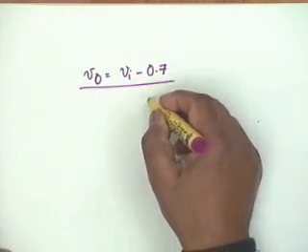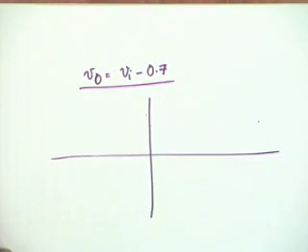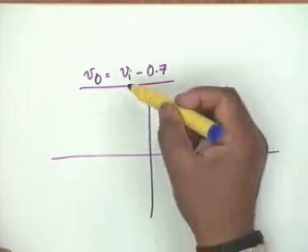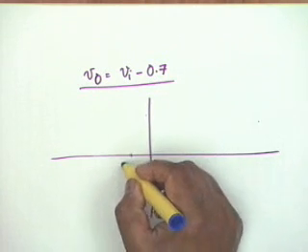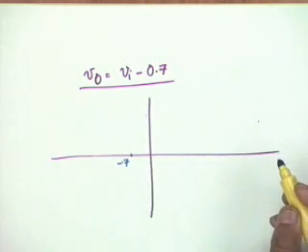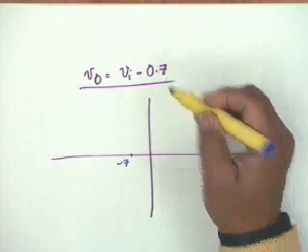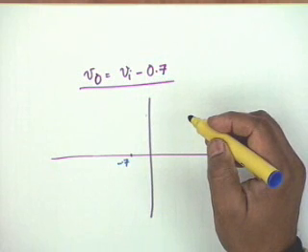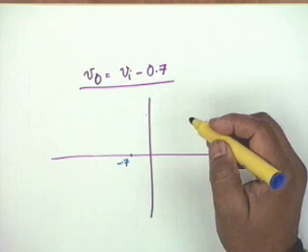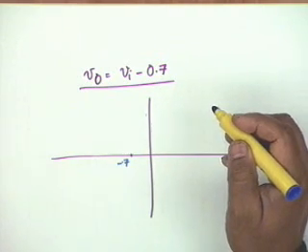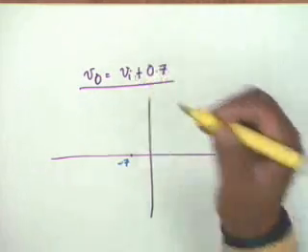Alright. Now if I draw the transfer characteristic, you see that when Vi equal to 0, V0 is minus 0.7. So the characteristic starts from here. When Vi equal to 0.7, so isn't 0 equal to Vi plus 0.7? That is correct.